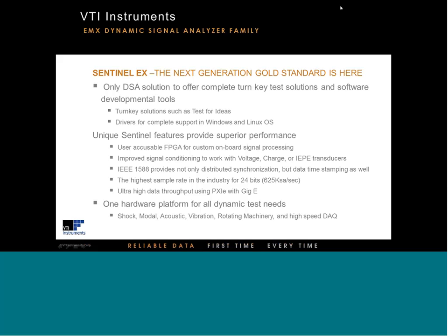With the Sentinel EX hardware, we do have some new things. Similar to our VXI products, we used to have a DSP that we could use for custom onboard processing. We've put in a large FPGA in each one of our cards, and we have some future capability that will allow users to be able to take advantage of that. We've improved the capability from a signal conditioning standpoint. Not only do we have the ability to do IEPE and voltage measurements, but also charge.